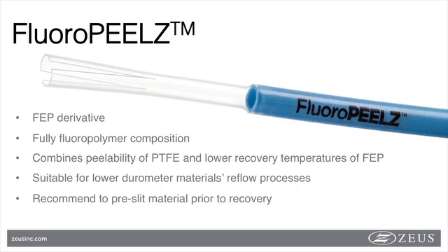However, it is very difficult to remove post-recovery, especially when the substrate is comprised of softer material. When trying to skive FEP heat shrink off after the recovery, one runs the risk of damaging the underlying shaft and scrapping the whole assembly. To combat such production issues, the evolution of fluoropolymer heat shrinks has allowed for the engineering of fluoropeels.